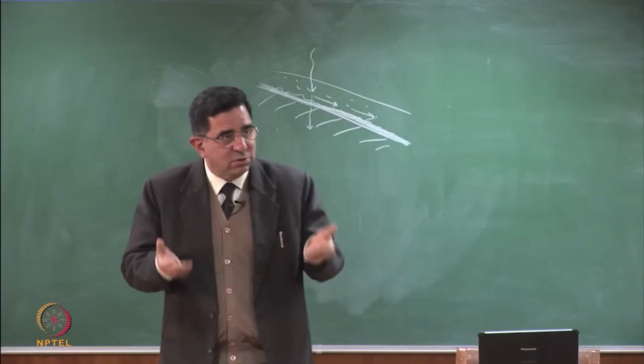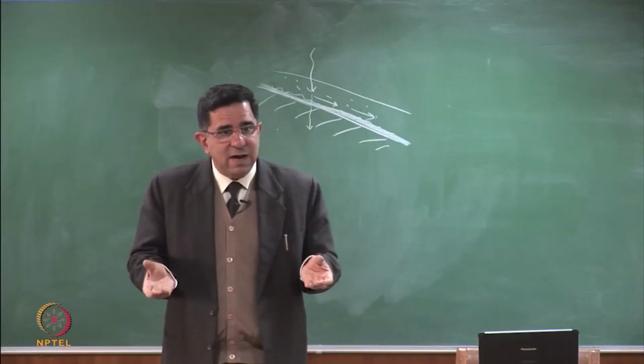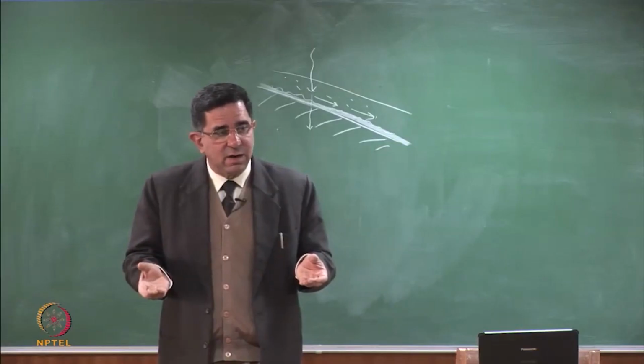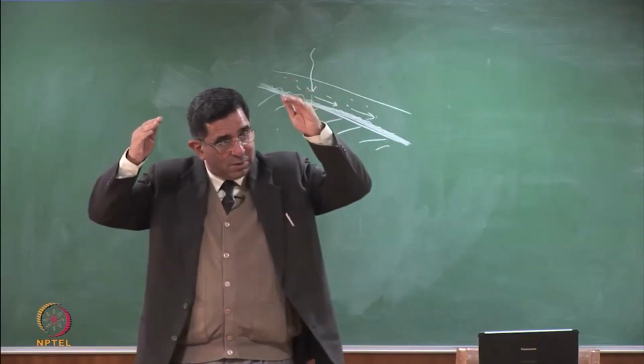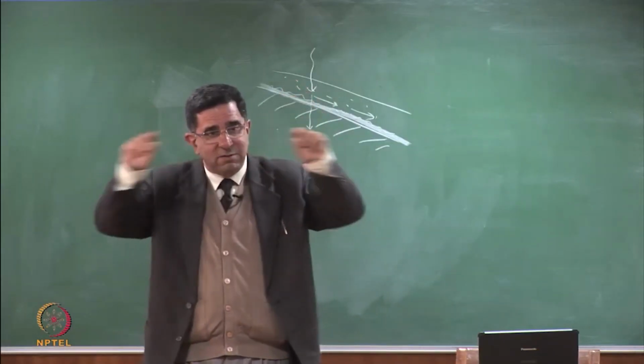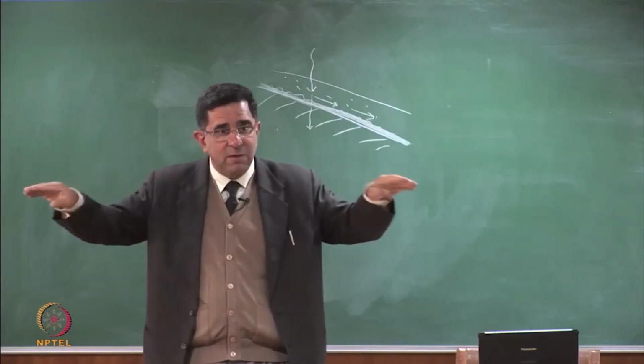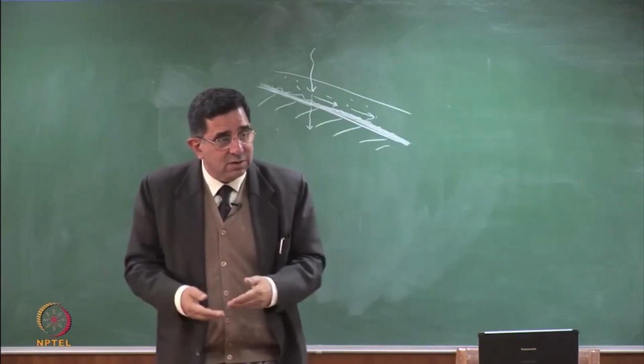Because in the liner system also there is a gravel and sand drainage layer, the leachate collection layer. If I can have water coming from rain into the top of the cover and replace the sand with a geocomposite which allows in-plane flow of water, can I use it in the leachate collection layer?